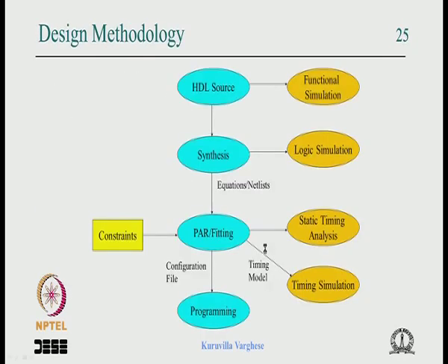So this is the place and route, and at that point the FPGA is a kind of general purpose circuit. The IO pins, your user input output signal can be assigned to any IO pin.